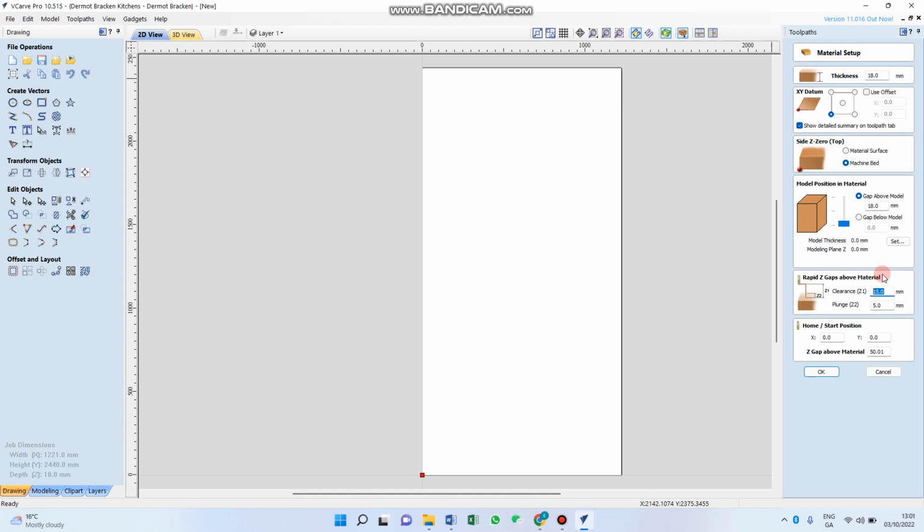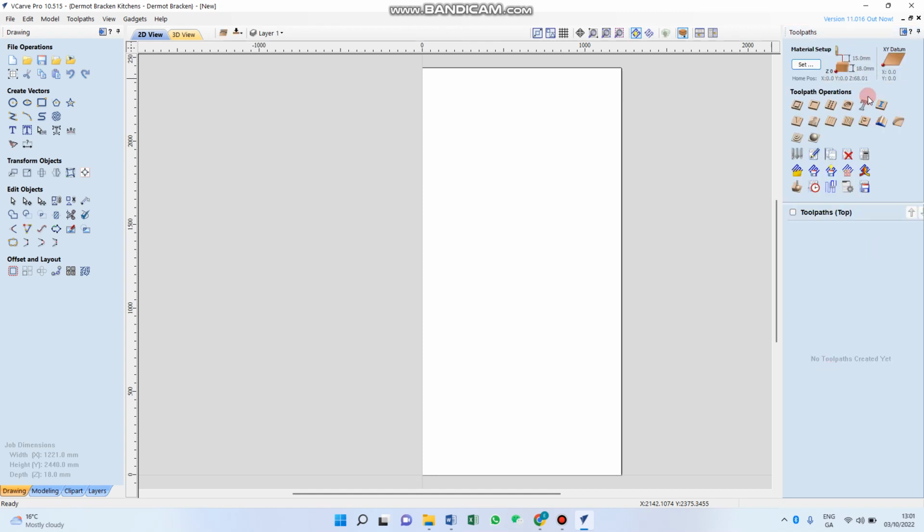And then obviously when you make a new set of programs, just sit and watch the machine as it does the first sheet, just to make sure that it's all working right. You'll know fairly quick if it's going too deep anyway. But at least if you have this set to 15, you won't be doing any harm. That's kind of all you have to know for in there. And you can also quickly check it up here if you ever get wondering. It has the main information there.